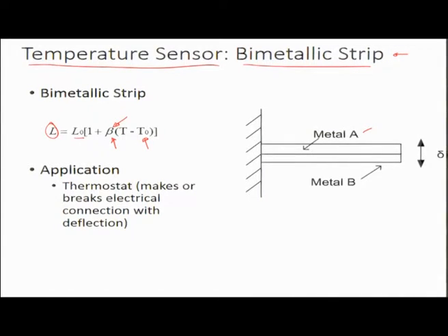So the idea is, if there are two different thermal expansivities of the metals, and they are stuck together, the only way to ensure that these metals are still maintaining contact is if the metal assembly, or the metal stack here, bends up or down. Such bending may lead to either de-switching, or loss of contact, electrical breakdowns, and so on and so forth. And it gives you an idea of the temperature beyond which the electrical breakdown should happen.